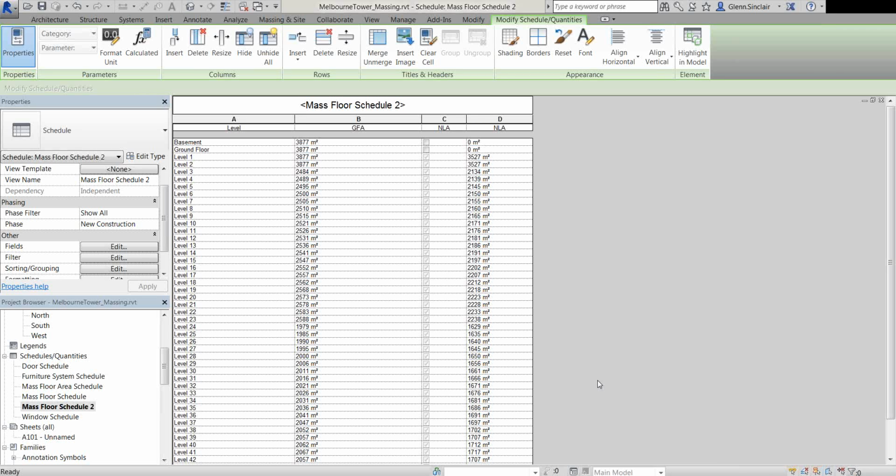As long as you're on subscription, you can get an Autodesk 360 account, which gives you access to the rendering. Now, it's not a free service, so you get around 100 credits with each license, and it uses these cloud credits. One of those still renders costs 1 credit. One of those panoramas costs between 5 and 7 credits. So you get your 100 with each license, and then if you use that 100, you pay $150 for 100 more credits. So they work out about $1.50 each. So you say one of those still images costs $1.50, one of those panoramas costs between $7 and $10.